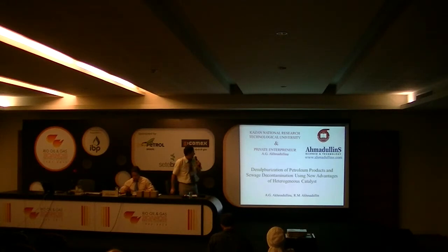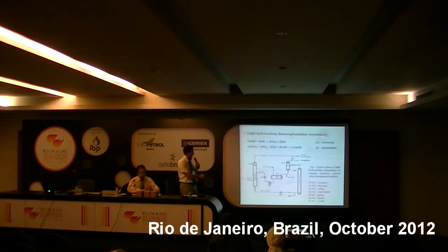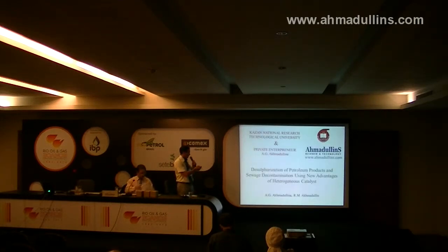Let me start my report concerning the desulphurization of petroleum products and sewage decontamination using new advantages of heterogeneous catalysis. Light hydrocarbons purification is based on mercaptan extraction using alkaline solution with the following regeneration by oxidation of alkali mercaptans to disulfide in the presence of catalyst.